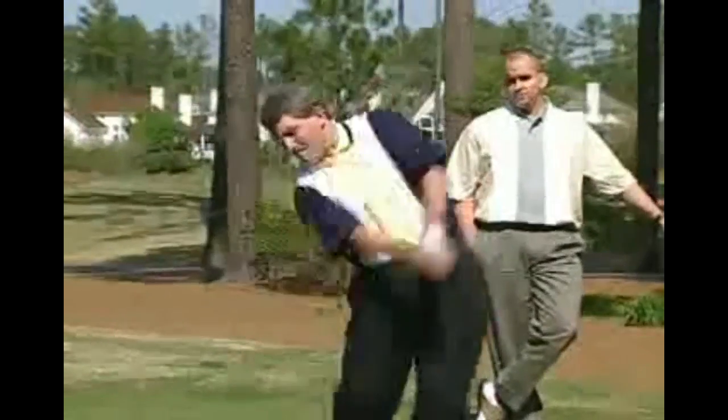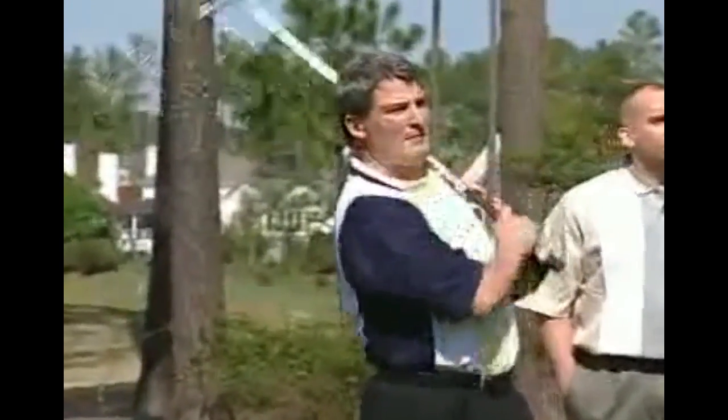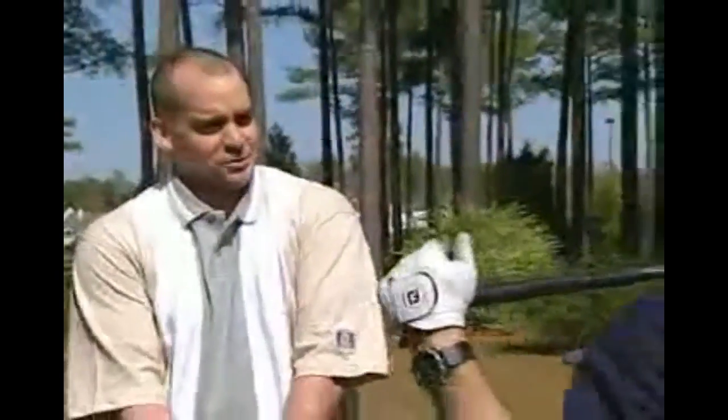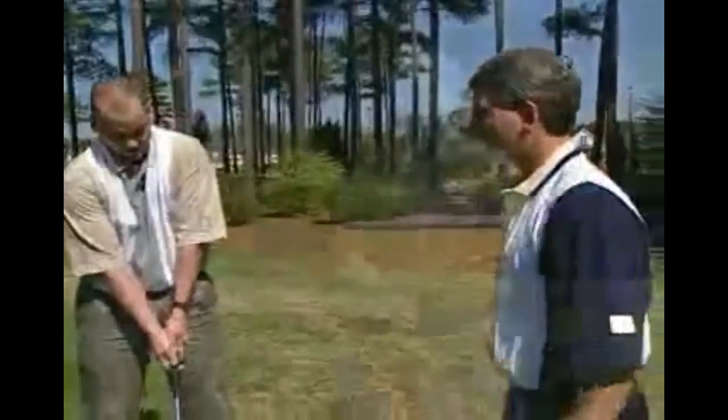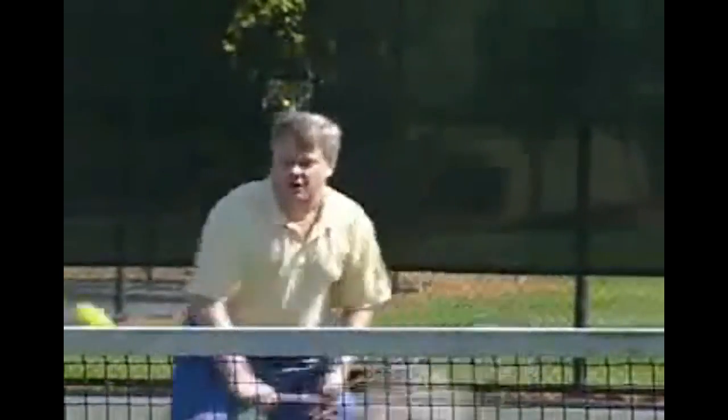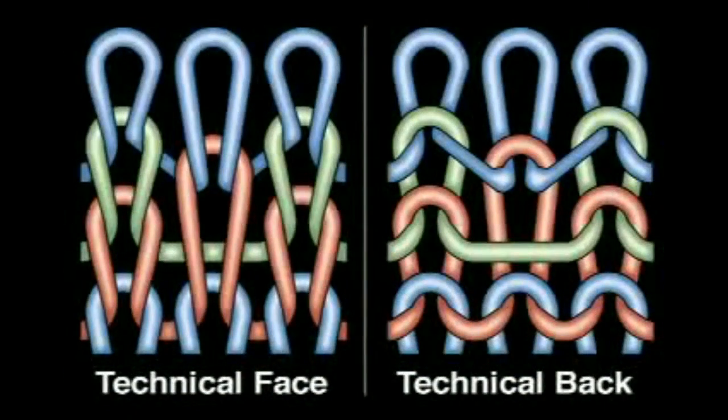Tucks are the basis for piqué, typically used for golf and tennis shirts, which need to breathe, retain their shape, but have some stretch. A wide range of piqué constructions can be made depending on the use and frequency of tuck stitches. The third type of stitch is the float, which is also called a misstitch.